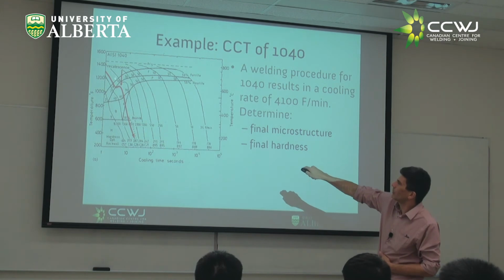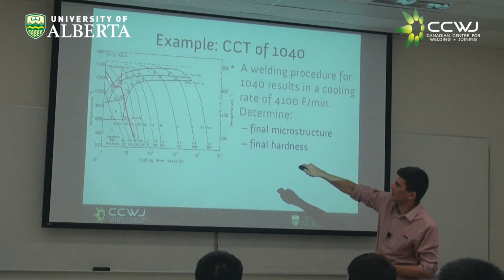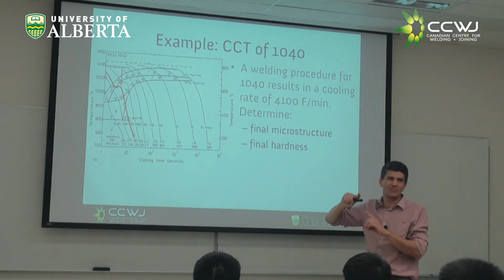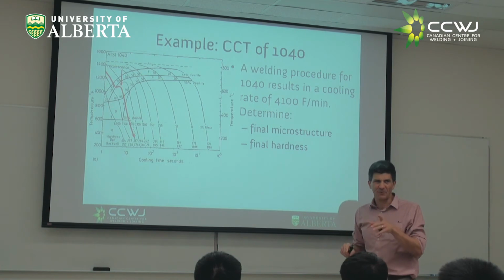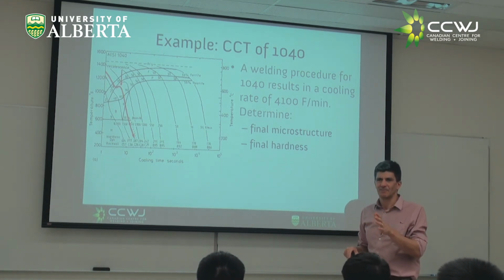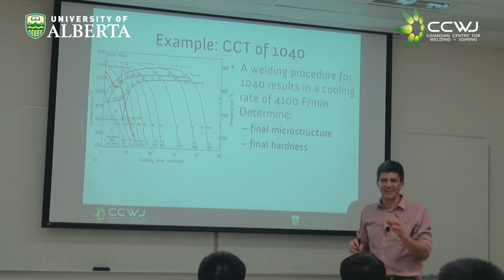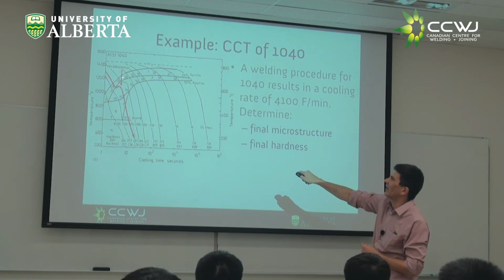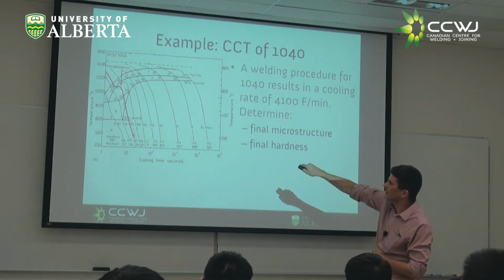I would start looking from up here. This is 100% austenite. What do I have here? Yes, 92% austenite plus 8% primary ferrite. Where does it nucleate? Grain boundaries, right? You start having a microstructure in your mind. You can even make a drawing. Then you keep cooling. Let's forget this hump there.